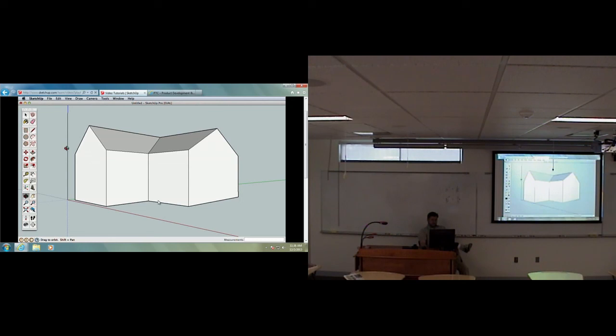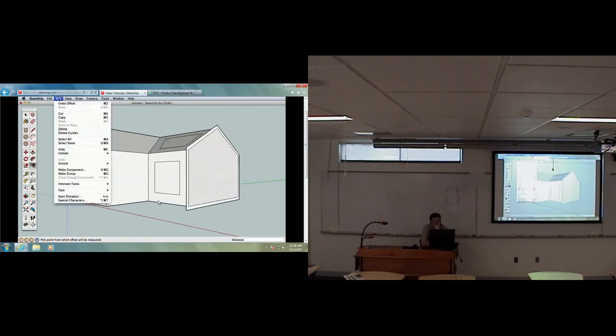To see how the offset tool works, click on the side of our house and pull inwards or away. All the edges of the surface are offset. Click to finish. You can try this on different surfaces to see the results, or if you wanted to focus on one surface, you could use the Select tool to pick a single surface, then the Offset tool will only work on that surface. Time to get back to our house.